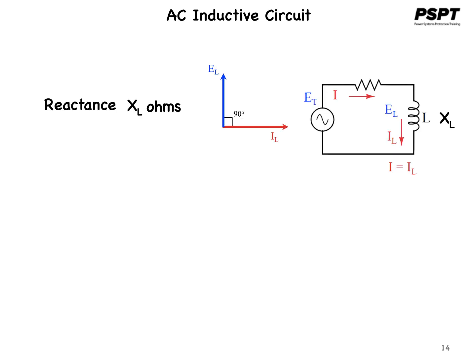We have already seen the relationship between voltage drop across an inductor and the current through it. That is, the voltage will lead the current by 90 degrees. The inductor of a given size will impede AC current similar to the resistance of a resistor. That resistance is defined by Ohm's law to be proportional to the voltage across it divided by the current through it. In phasor terms, it is defined by the voltage phasor divided by the current phasor, and is in phase with the current.